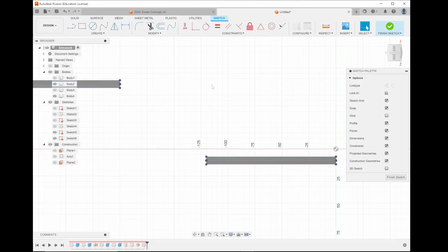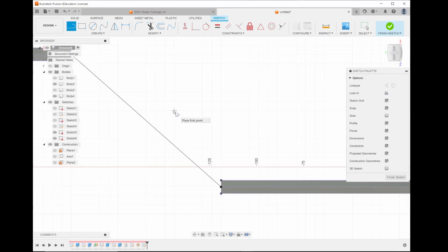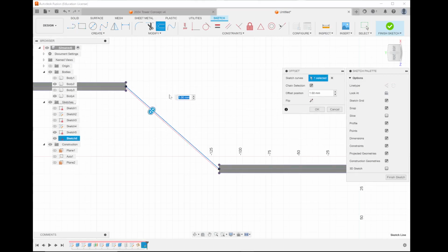So we have these shapes over here, and now we're going to click the middle, and the middle will go to here. And so when we make our balsa wood, what's the dimension of a balsa wood? 5 by 5, right? So when we make it, we can actually press the offset. If we press offset over here, this is the middle of the balsa wood. So how far are we in one direction? 2.5, yes, 2.5. And we press OK.